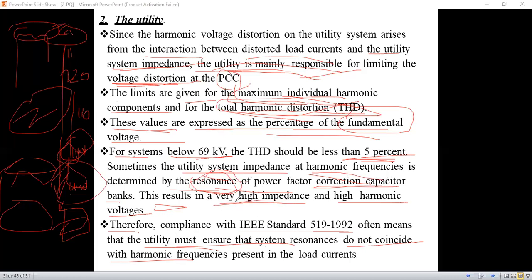So high impedance will cause high harmonic voltage to increase here now. We have to ensure, by using the many components we can use, that the resonant frequency and harmonic frequency do not coincide with each other. Then we can control that. Now, according to IEEE standard 519, they have told us...